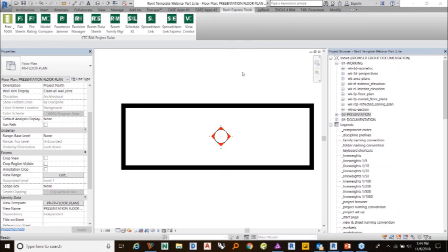So if you have really complicated formulas, you can do it that way. I do have one thing to say about that, which is that if you're putting a CSV into a Revit file, you want to make sure that the elements are not actually being tagged in the actual model, and you are separating the 3D from the actual schedule that you're importing in. So that's just something to think about. There are ways to try and tie them together, but it becomes complicated. If it's too complicated, I totally understand, and it might be faster to just build that schedule in.